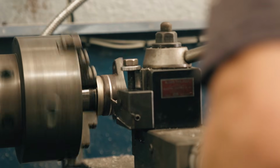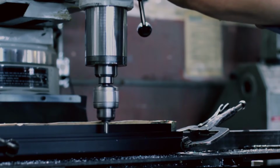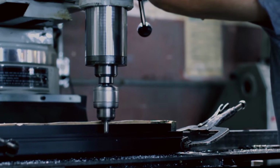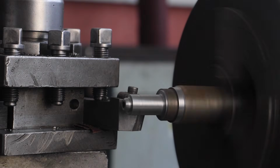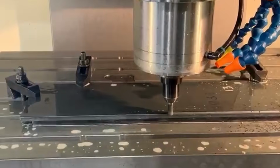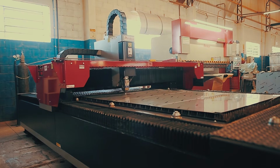And the second perspective is the manufacturing perspective, that during the machine design we have to consider how the part is to be manufactured. And most importantly, we have to understand the manufacturing process and each machining step of that particular part. Like how the part will be located in the machine's tool, like what will be the resting face of the part.